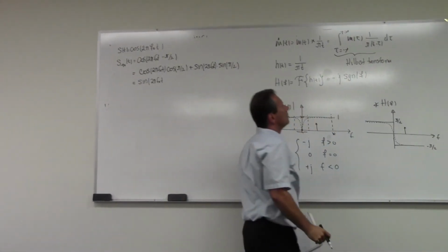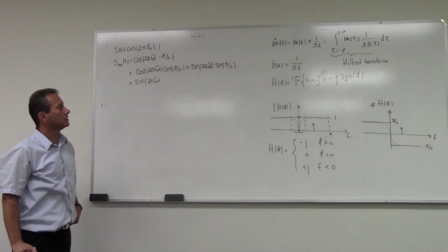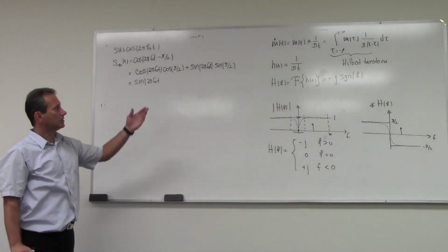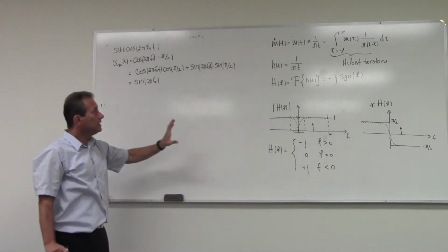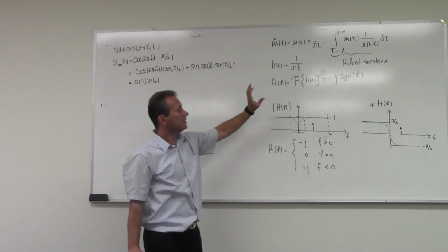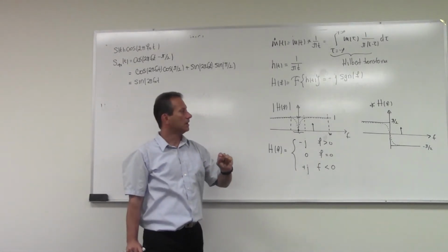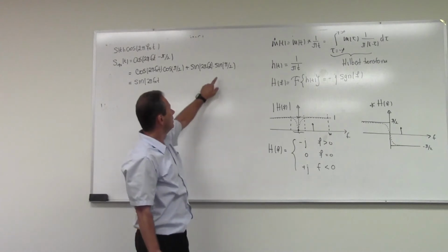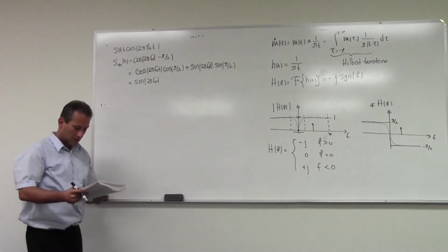It's an integral transform, a linear transform, very similar to a Fourier transform or Laplace transform. It has very interesting properties on its own. But for what we need here, we have to understand that the Hilbert transform takes every spectral component of your signal and delays its phase by pi over 2, turning essentially every cosine into a sine.